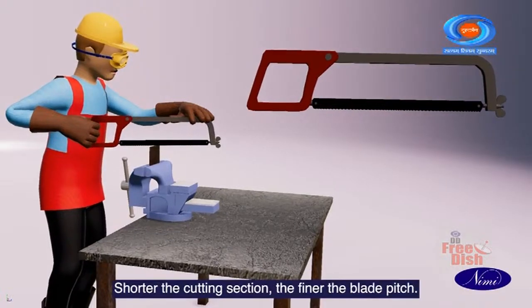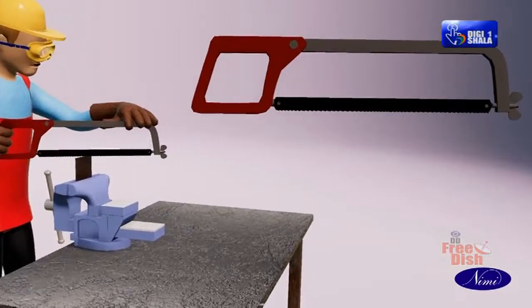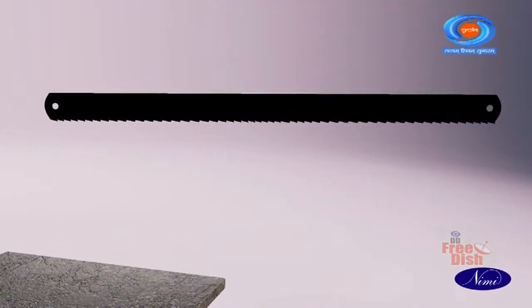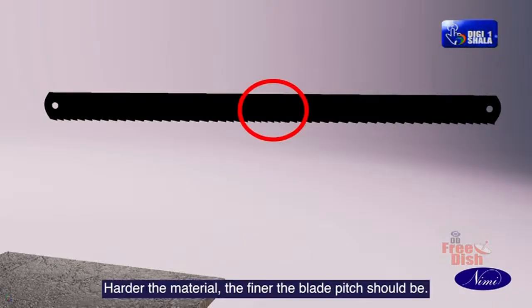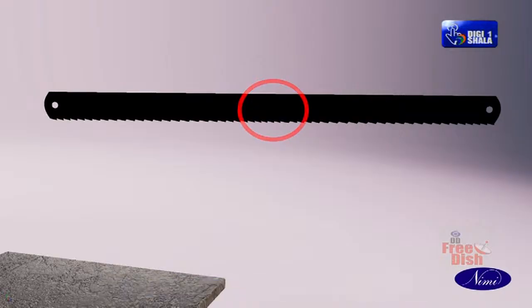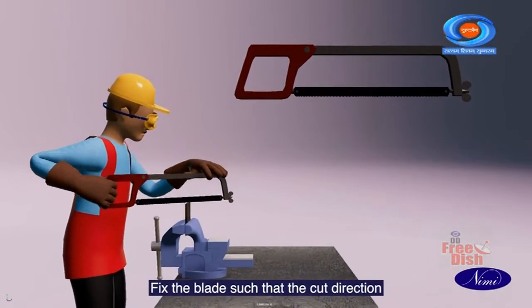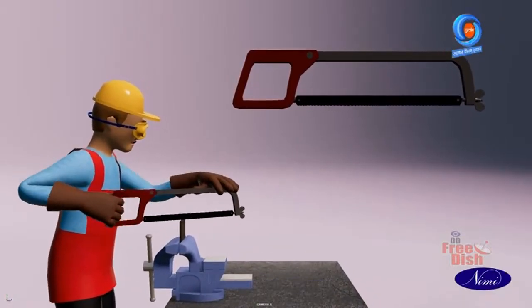Shorter the cutting section, the finer the blade pitch. Make sure that at least 4 teeth are cut at a time. Harder the material, the finer the blade pitch should be. Fix the blade such that the cut direction is towards the teeth.